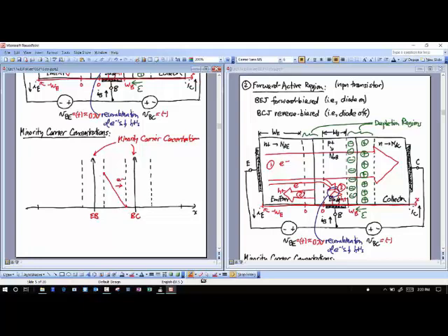And so, because of recombination in the base, you can derive that the density of electrons starts looking like just a straight line. Now if the base were wider, and if you're taking 130, you'll see that in actuality this is not just a straight line. It actually comes down and flattens out if you have a very wide base. But right now I want to keep it simple, and inevitably, if you're designing a bipolar transistor, you're going to make your base as thin as possible. You will not make it wide. So it will look like the straight line there.